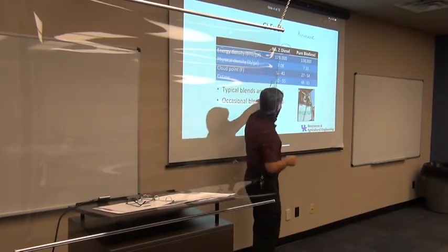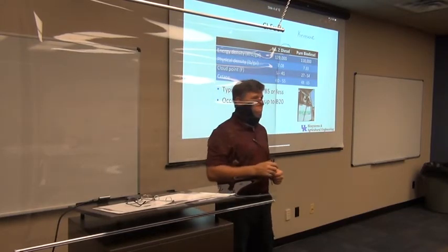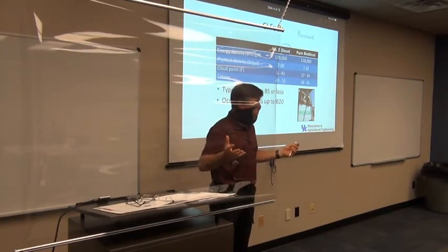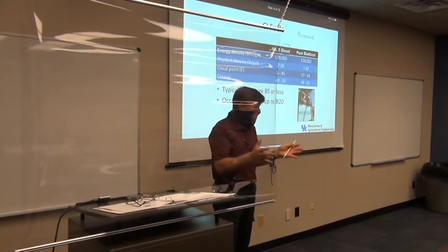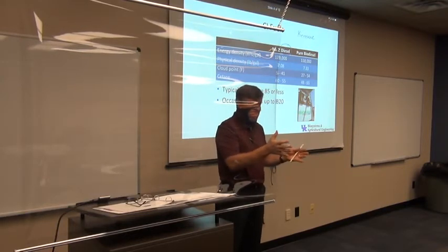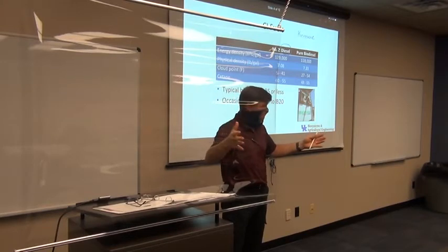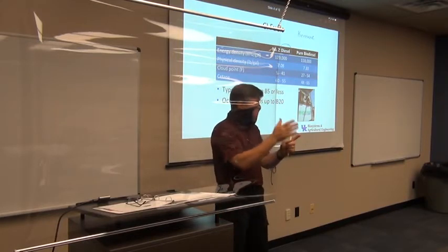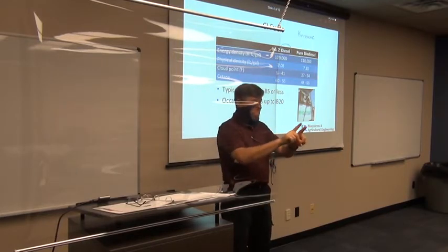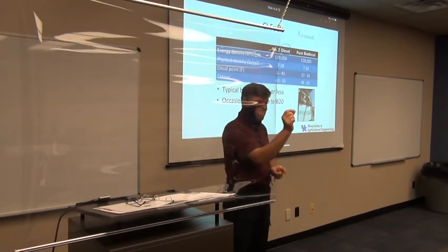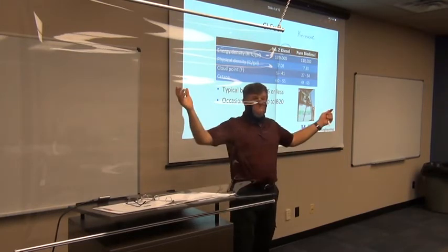Here's the thing. Look at the range on that. What's interesting when you look at what constitutes diesel is that it can be a lot of different junk. It's really the standards, and we talk about standards for how you define what is classified as diesel. Those standards are really broad. When you go to gasoline, the standards are very tight. So when you go to a pump, with different manufacturers and brands of fuel, there's not a whole lot of variation from one fuel to the other. They're all going to be very similar. Cloud points and all those specifications have to be very tight. When you go to diesel fuel, it's kind of wide open.